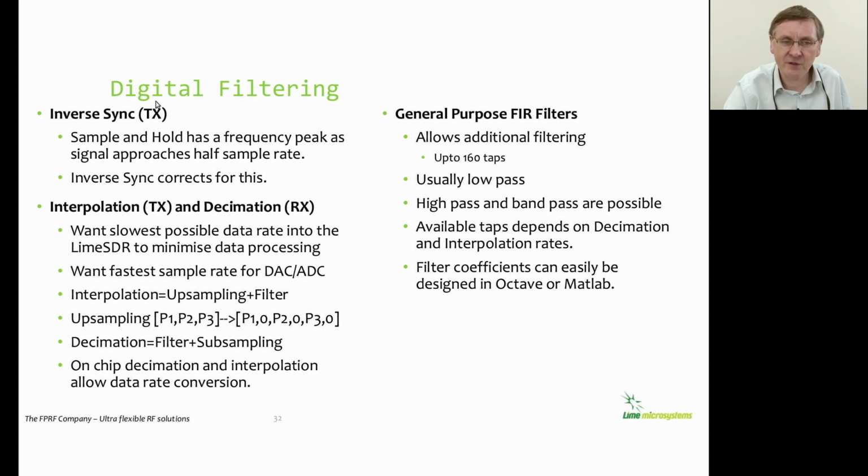So why do we need some of these blocks? Inverse sinc corrects the behavior that occurs in sample and hold systems, which means that as the signal approaches the sample rate, the signal tends to droop. So basically it's just a digital filter.